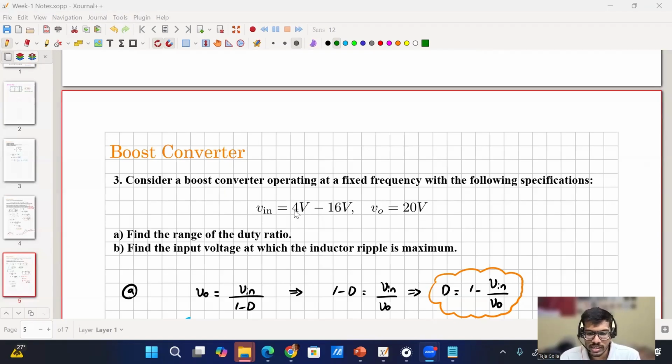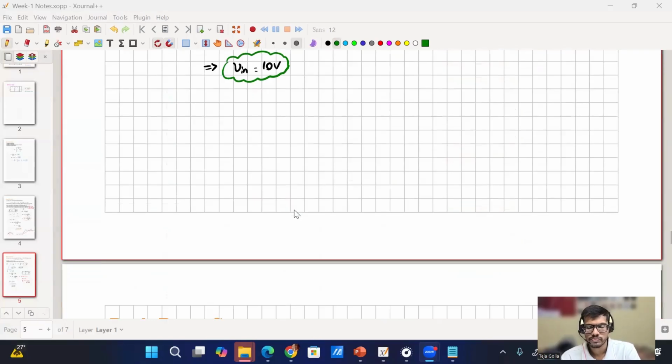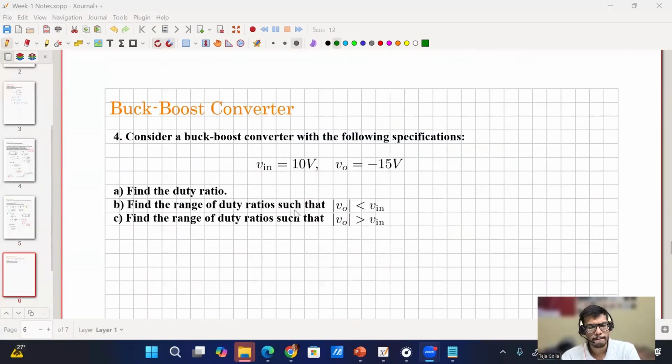Say if it is not falling in that range, then you have to see up to what duty ratio we can go, and then check at that condition. Because if I choose V in to be 12 volt to 16 volt, in that case D equal to 0.5 is not possible, so it will be slightly different. These more complicated problems we will solve in the upcoming weeks, so don't worry. In this week it is simple things, so we'll start with simple design. Okay, fine. Any queries?